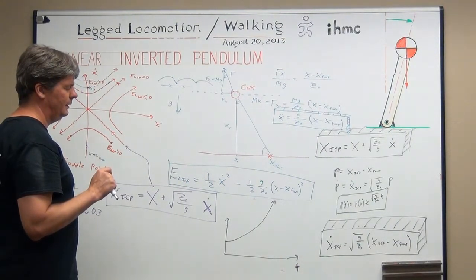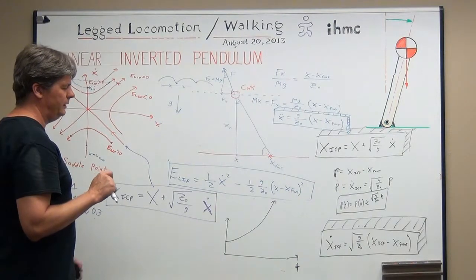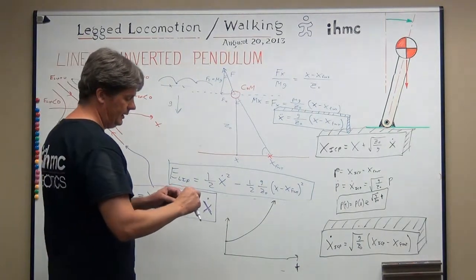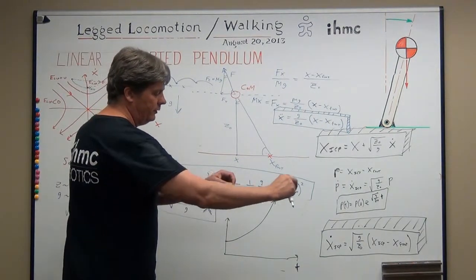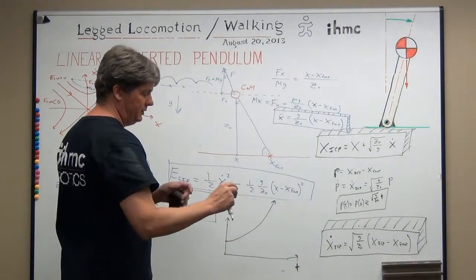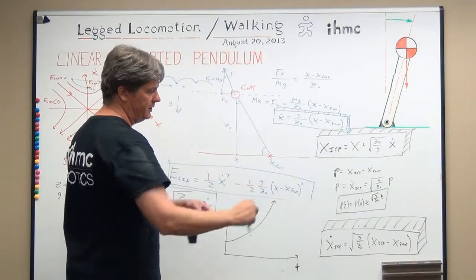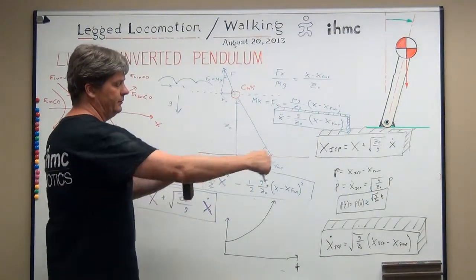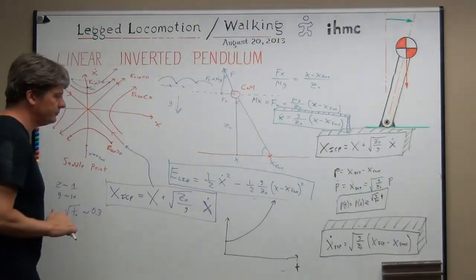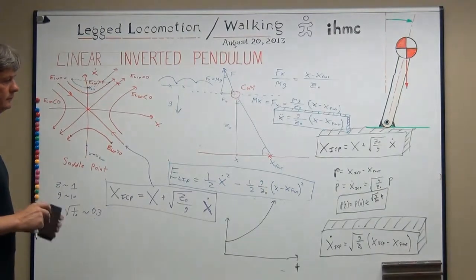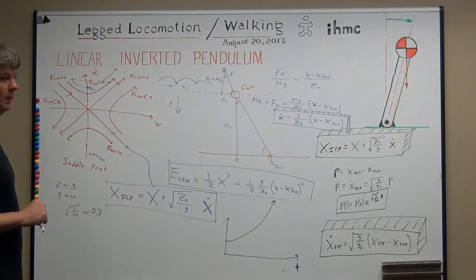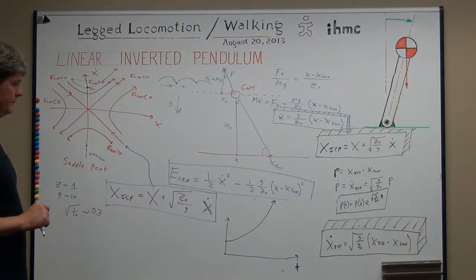Do they move together, apart? Your instantaneous capture point is going to keep getting further and further away from you until you step. So your instantaneous capture point is actually moving faster than your velocity, right? Yes, because it keeps getting further and further away from you. So, this exponential grows, but at time zero, you're at the place where you're stepping, right?